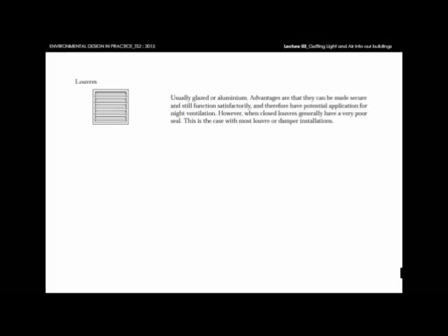Whichever you have, I would like you to very accurately measure that in terms of understanding how the window opens, and when it's at its full opening, or the one that you generally use, what actually is the effective area, and then what is the relationship of that effective area to the area of your room. Essentially, you should be looking at 5%. Have you reached 5%? That's what I want to know.